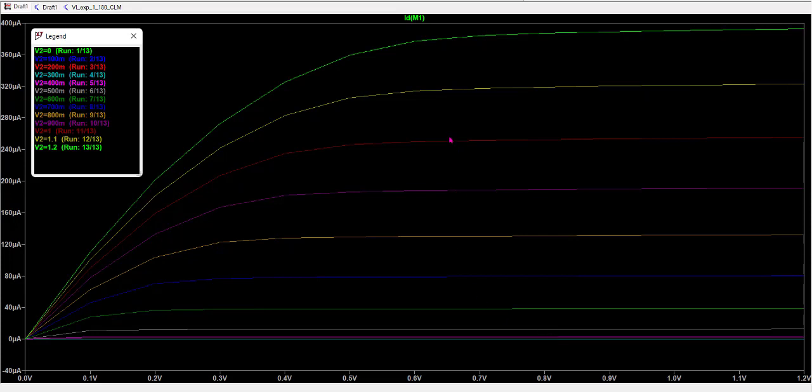So as we keep on increasing the value of VGS, the inversion layer will have more charges, and therefore the current will increase. But since we are also increasing VDS here, the increment of VDS will pinch off the channel, and once it pinches off the channel, the current can no longer increase, but the current is not zero. What will happen?